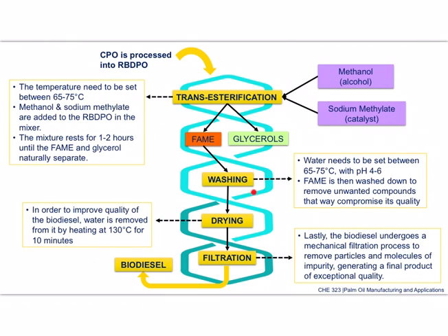Once the pH of this fatty acid methyl ester becomes almost 7, the next step is you need to dry the fatty acid methyl ester, because previously you washed with water, so you're going to have water in your oil. Therefore you need to dry your product. In the plant design that you have, you're going to dry it using a vacuum dryer.